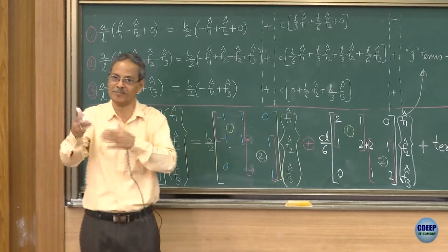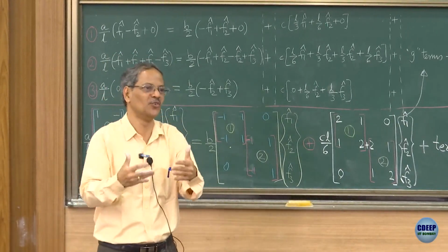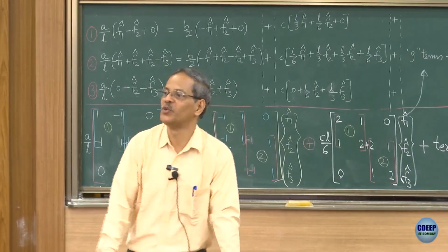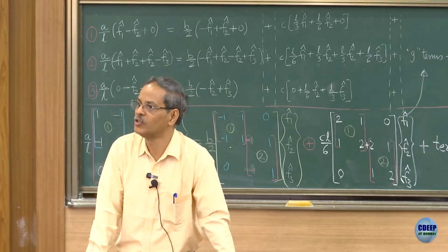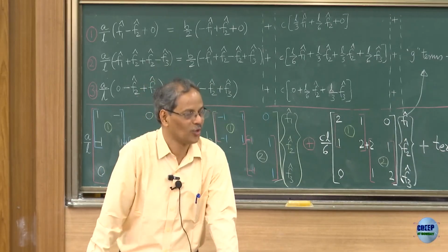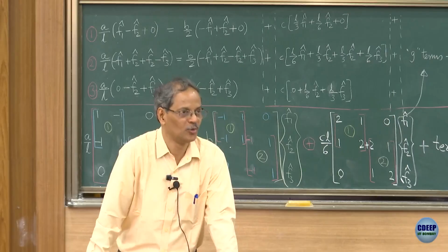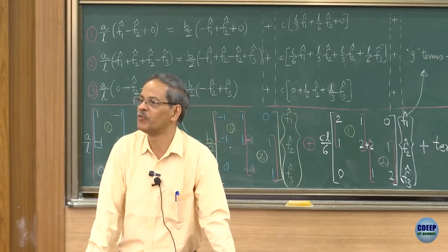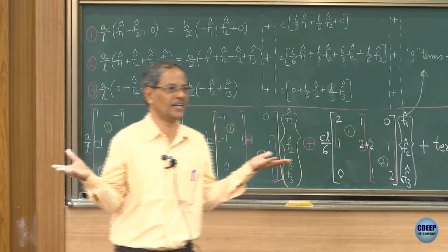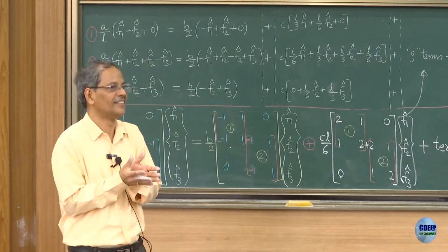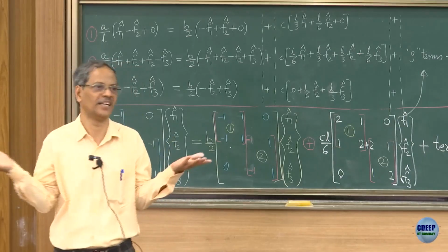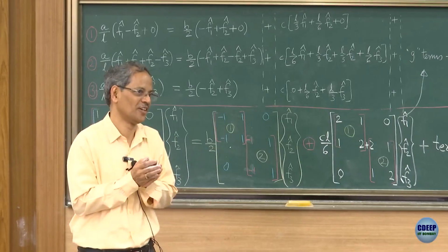If your differential equation is good, and you follow Galerkin's idea of W being same as the shape functions, then you would get all of them to be symmetric. When it is symmetric, then you know the computational storage advantages and solution advantages, all those things are there.